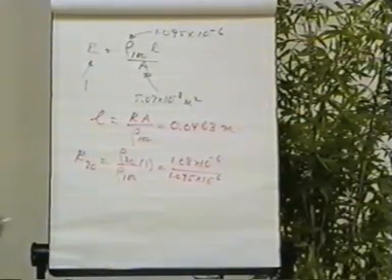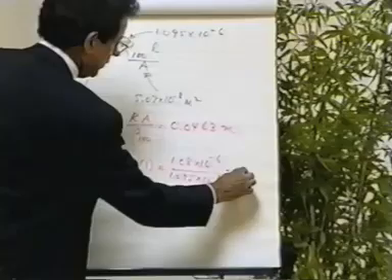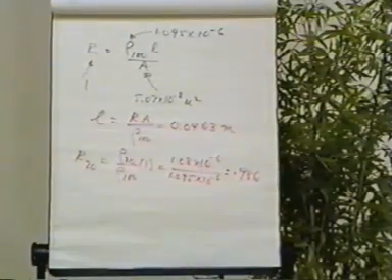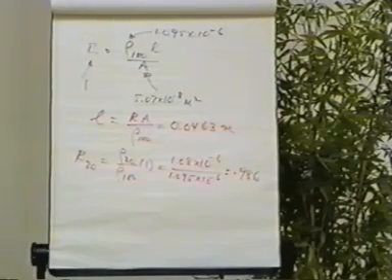This ratio gives us 0.986. That would be the resistance of that same piece of nichrome at 20 degrees, a little less than it was at 100 degrees, went from 1 ohm down to 0.986 ohms.